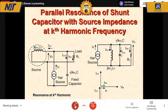If they do resonate at the kth harmonic, then what we will realize is, look at the phasor diagram. Vn is the nth harmonic voltage appearing across the load, because now the fundamental is not there. I'm applying superposition theorem. I am looking only at the kth harmonic system. Because of superposition theorem, I am not looking into the fundamental. So this is Vn. IRN is the harmonic current, part of that is flowing in here. But because they are having parallel resonance, the current in them can be individually very large. So you have ISN very large, and that is equal to ICN. So individually, the currents will cancel out with each other.